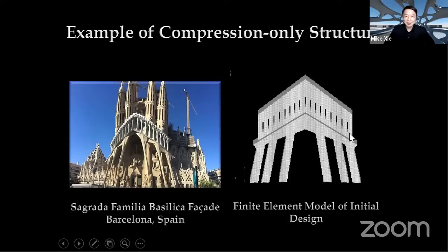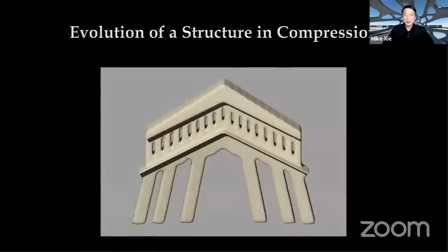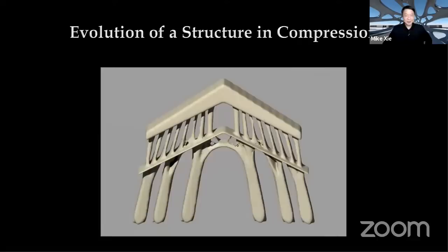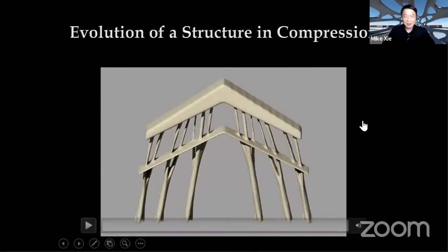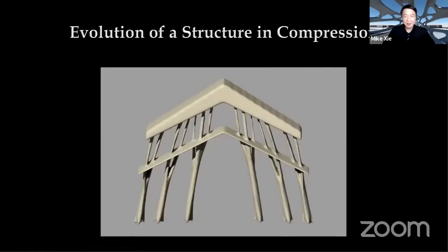So we apply all the loads, and because this structure is made of stone, you want the structure to be in compression. So all we need to do is, every step, we remove the material with the highest tensile stress, and you will see such a process. And with Mark, we did a lot of analysis of the shapes Gaudi designed for that church, and we found amazing